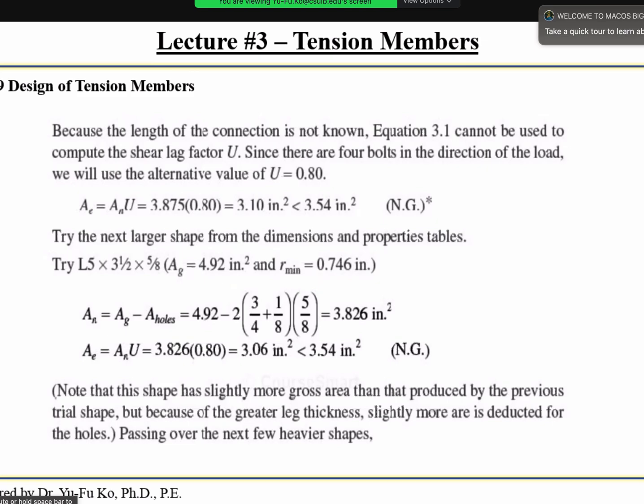Well, I think XX and YY will be the same if it's symmetric, right? It depends on what kind of symmetry we are talking about. If X and Y are both symmetric, the dimension is the same, then yes, they are the same. But typically, it will not be the case in steel design. My manual still has a ZZ section for symmetric ones, so just ignore that ZZ completely. We don't need that value because that one is not minimum at all if the section is symmetric. So that's why if you check the table, there's no RZZ for symmetric sections. Double symmetric I'm talking about.